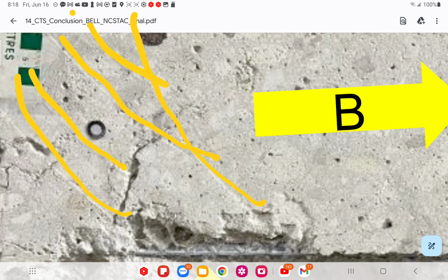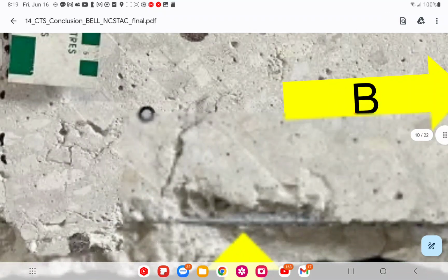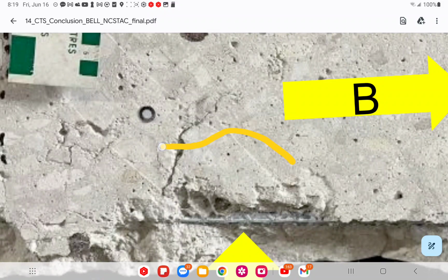And looking over here, these were where stones were that popped out. It's not honeycombing, it's where stones were in contact with the reinforcement. Keep in mind that there would be less paste there when the stones are touching your reinforcement. And so here you would indicate probably more exposed, less paste. Because the stones are literally touching that area, it's still got great bond force around it.